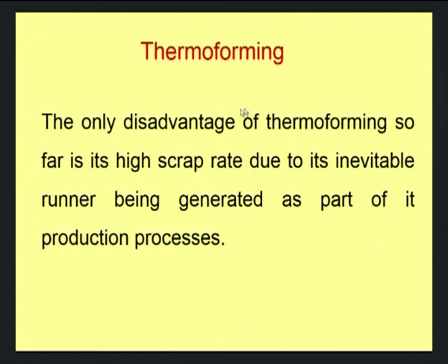Now, if you look into the disadvantage of thermoforming, the disadvantage is only the high scrap rate due to the inevitable runner being generated as part of the production process. As we have seen earlier, the runner or the skeleton that comes out along with the product has to be trimmed and then it has to be recycled. So, the runner or the skeleton is softened 2 times, one time during the thermoforming process, the other time when you want to reuse it, you have to prepare it as a sheet, there again you have to melt it. So, therefore, that is the only disadvantage with respect to thermoforming.